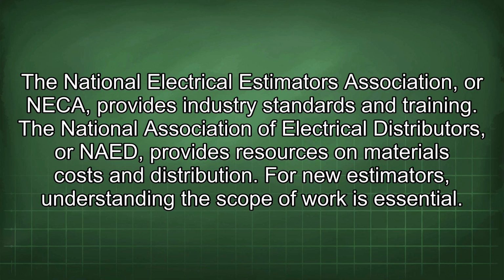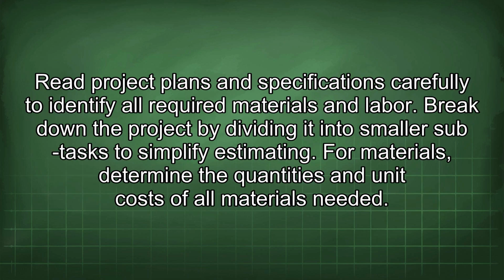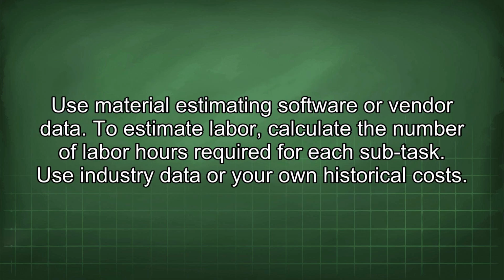For new estimators, understanding the scope of work is essential. Read project plans and specifications carefully to identify all required materials and labor. Break down the project by dividing it into smaller subtasks to simplify estimating. For materials, determine the quantities and unit costs of all materials needed. Use material estimating software or vendor data.